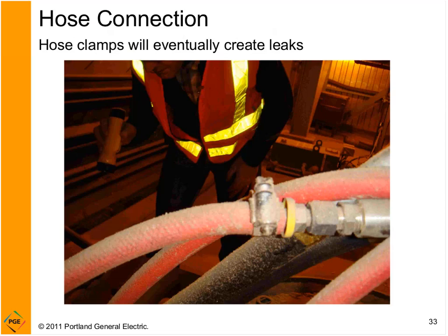Okay, this one is a poor choice for a hose clamp. Old-fashioned radiator hose clamp. And just like in your car, eventually they dig through the rubber and you have a leak. So use crimped, rounded-ended connectors instead so that you don't create a leak.